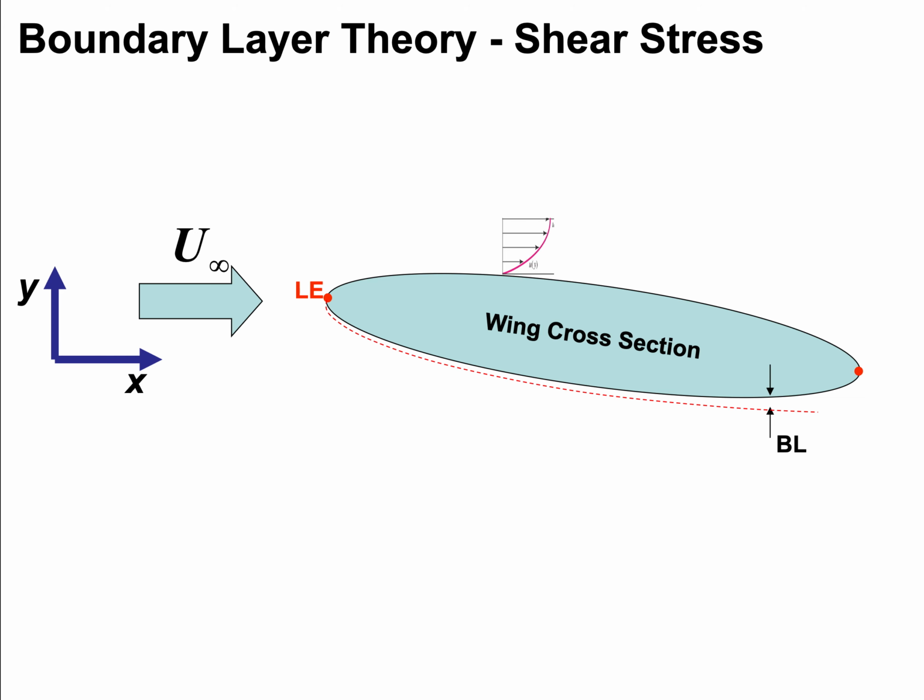the fluid element that's in touch with the object will have the same velocity as the impermeable solid object. And as we see from this cartoon, far away from the object, we expect that the air or water would be going past this wing at the undisturbed velocity of u infinity. So we have a region where our velocity would go from the no-slip zero velocity all the way to u infinity, and we get a velocity distribution,